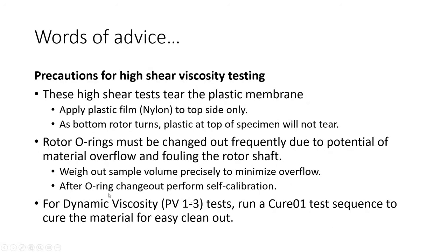But then after, you're going to have to change those things out and do a re-self calibration constantly with this. So it is a time-consuming test, and keep in mind, for the dynamic viscosity, the PV tests, it's really hard to take the material out until you cure it. So we just run a cure test afterwards to cure everything out and clean out the rheometer.